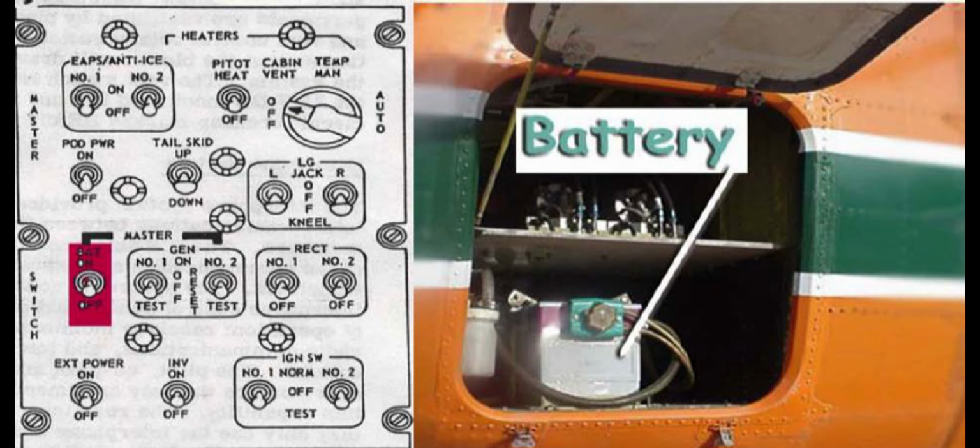Placing the switch in the off position will disconnect the battery power from the DC primary bus. Battery relay. The battery relay is bolted to the upper right beam in the nose electronics compartment at station 42. The relay is a single pole contactor relay. It applies 28 volts DC power from the battery to the primary bus.